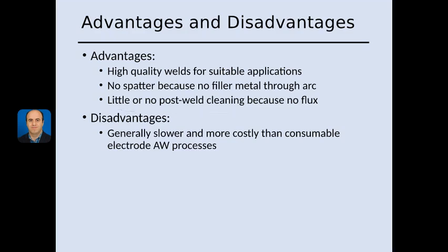The disadvantage is that this is slower than other arc welding processes, because mostly the process is done manually, and if the process requires filler, that is going to be even slower, because you have to feed the filler material.